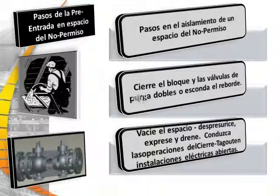Steps in isolating a non-permit space: close and double block and bleed valves, blank the flange, empty the space, depressurizing, ventilating, and draining, conducting lockout tagout operations on open electrical facilities.